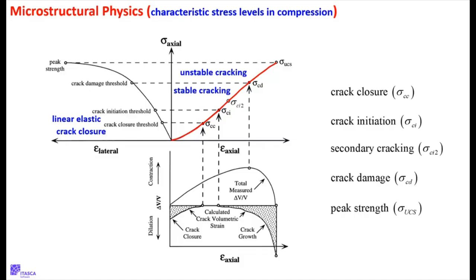Okay, so what do we have here? This is a uniaxial compressive strength test. I'm assuming you know all about this. You take a cylinder of rock, and they're usually really small. They're usually like 50 millimeter diameter, and often they're 100 millimeter height.